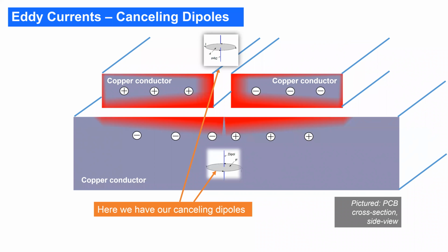If we think about the hot loop of a DC-to-DC converter, we usually have the loop current flowing in the top trace in one direction, and since it's always a closed loop, we also have the opposite direction. The current density between these two wires will concentrate in that area because we have opposite current. If we have a ground plane underneath, we will get an eddy current opposite to the top one, which in addition concentrates the current. So most of the current concentrates where the current in this direction finds its back-flowing current, and also here because of the opposite eddy current. I still have a little bit of current density at the outside from the skin effect, and we will come later to why that can also be a problem.